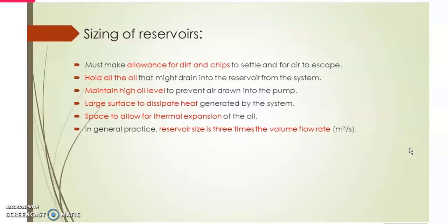Third, it must maintain a high oil level to prevent air being drawn into the pump. Also, it should have a large surface to dissipate heat generated by the system. And the last one, it should have space to allow for thermal expansion of the oil. So in general practice, the reservoir is 3 times the volume of the pump flow rate.